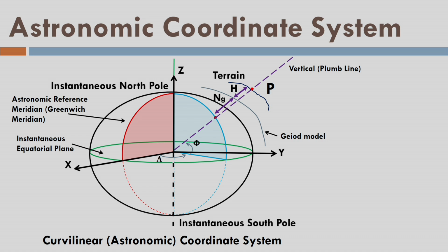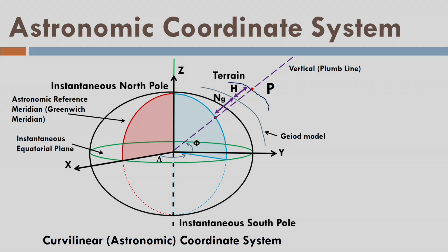Well, earlier we assumed for a regional ellipsoid that the vertical line and the ellipsoidal normal are parallel, or basically the same, and there was some reason for that, rather it was a limitation. Why? Because in those days when this concept of the ellipsoid came, there were no observations possible with respect to an ellipsoid. So what scientists used to do was fit an ellipsoid of defined parameters. That means they had already fixed the ellipsoid.